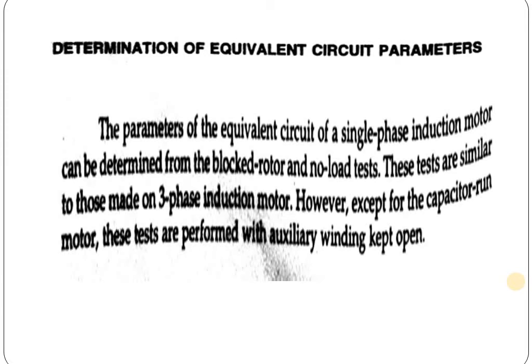The parameters of the equivalent circuit of the induction motor can be determined from the block rotor and no load test. These tests are similar to those made on a three-phase induction motor. However, except for the capacitor motor, these tests are performed with the auxiliary winding open.